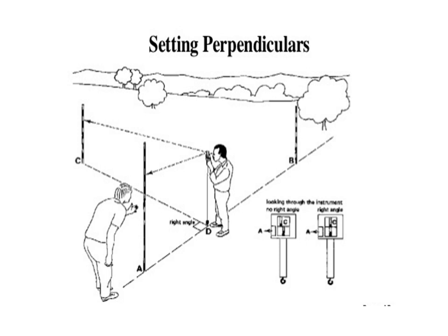And for that we are supposed to hold the ranging rod at A and C. So simultaneously 2 persons are required, and one is going to hold the ranging rod at position A. Similarly, another person is going to hold the ranging rod at position C, and when they meet and coincide, then the point D is the foot of the perpendicular for that particular offset, and the distance AD is the chainage of point D.